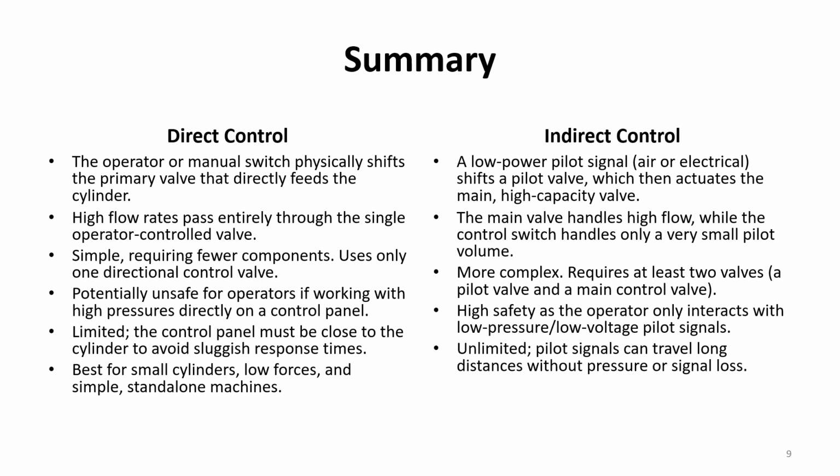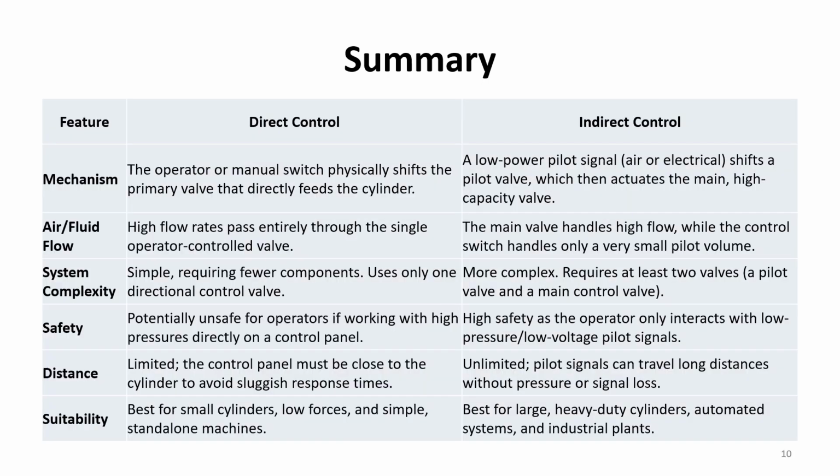And as for suitability, direct control of cylinders is suited for smaller cylinders, low forces, low pressure, simple and standalone systems, which are potentially safe to operate at lower pressure conditions. Whereas indirect control circuits are suited for larger applications which require heavy duty cylinders operating at high flow rate and high pressure, mostly in industrial automation systems.